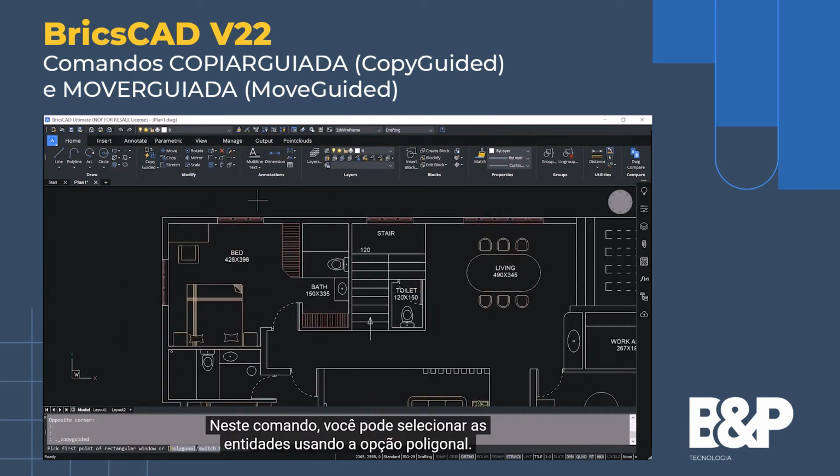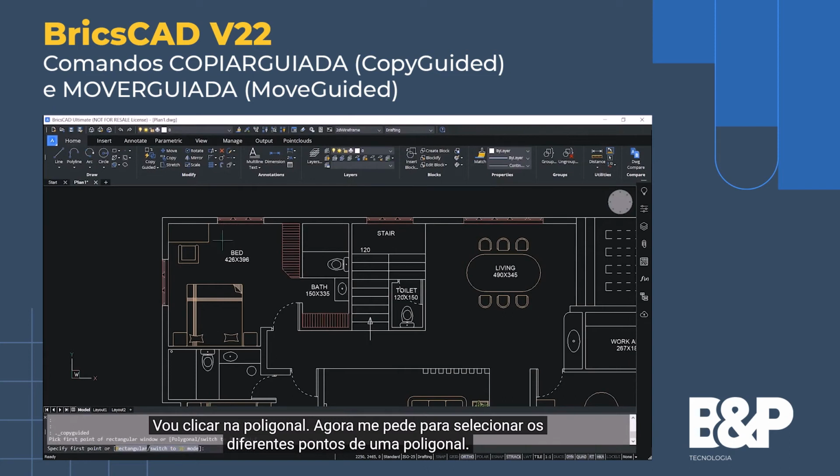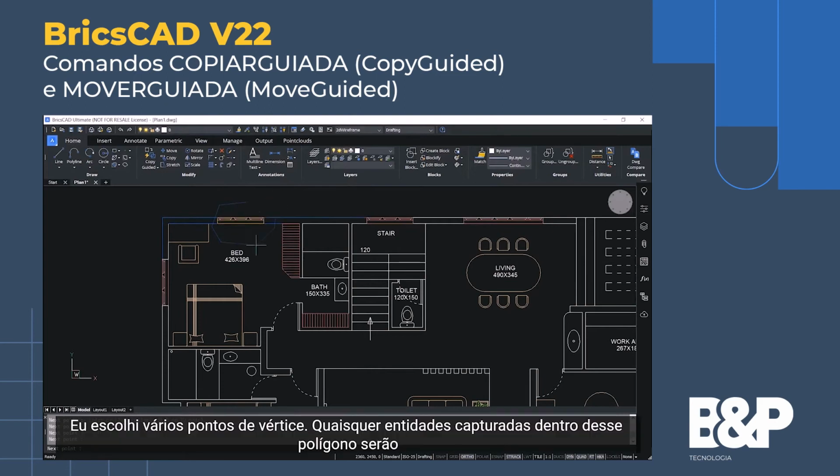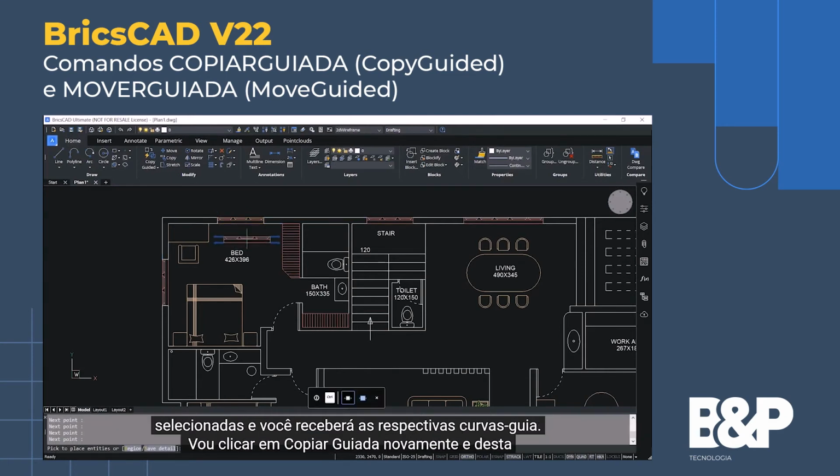In this command, you can select the entities using the polygonal option. I'll click on polygonal. Now I'm asked to select the different corner points of a polygon. I've picked a number of corner points. Whichever entities are captured within this polygon will get selected, and you will get the corresponding guide curves.